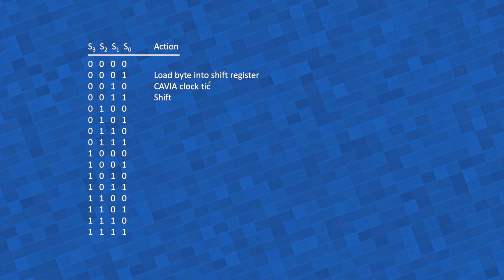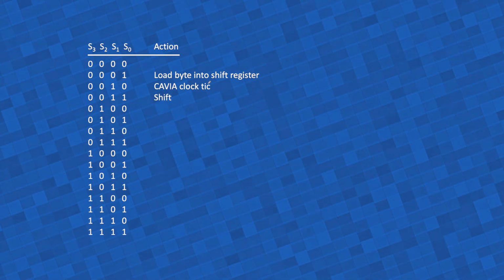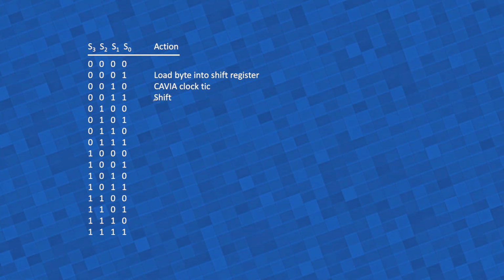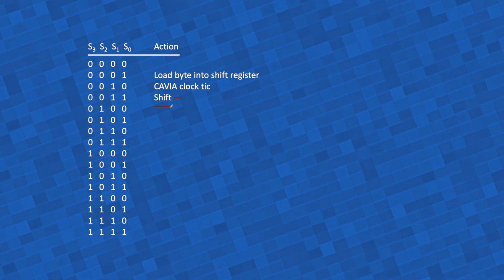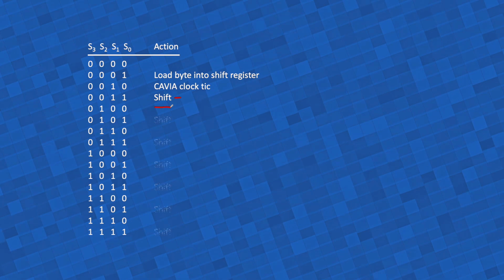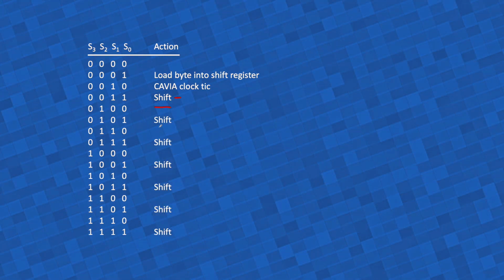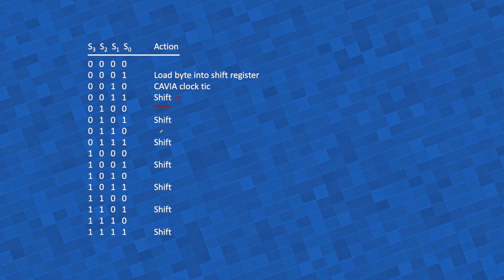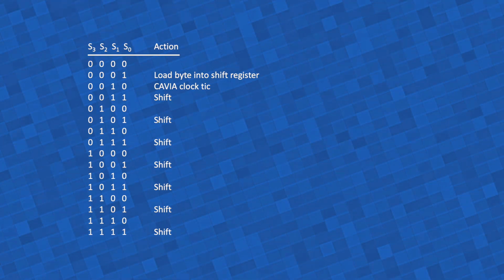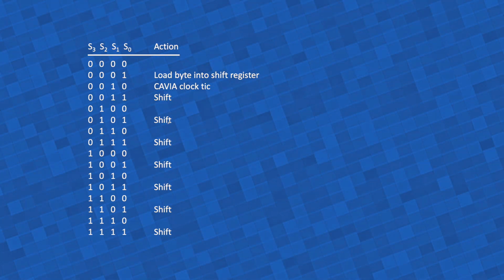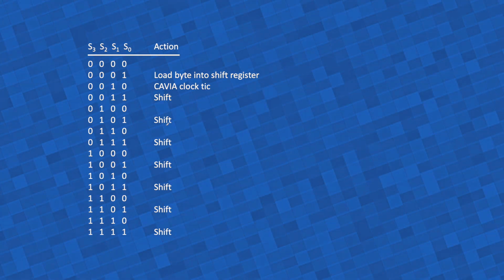In other words, we have to shift the contents of the shift register. And then the new bit is presented once here, and it will be presented here. So the next shift should happen there, and so on and so forth, always with an empty cycle in between, because remember, the shift register clock should be half of the pixel clock. And this is what you see here.